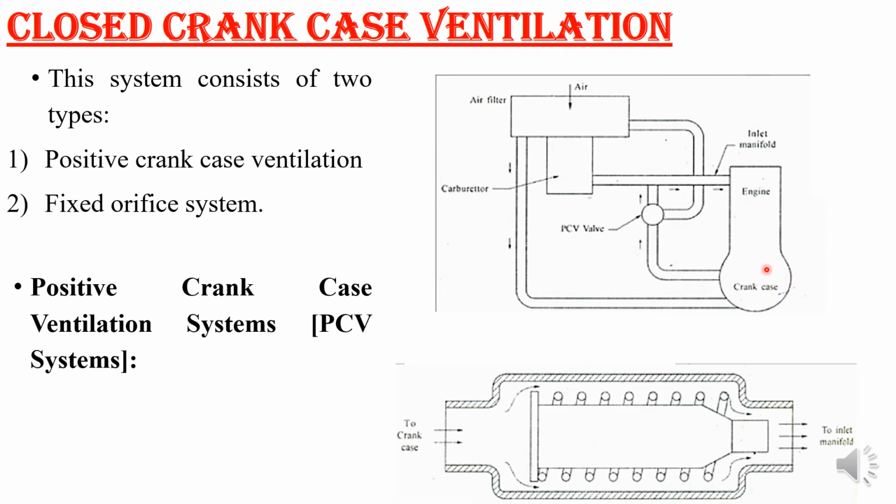As the engine oil circulates, it also carries blow-by and some burnt particles which form from the incomplete combustion of the air-fuel mixture in the crankcase. If it is not removed, this will dilute the engine oil, and hence the oil does not lubricate the engine properly, and wearing of the parts will take place.